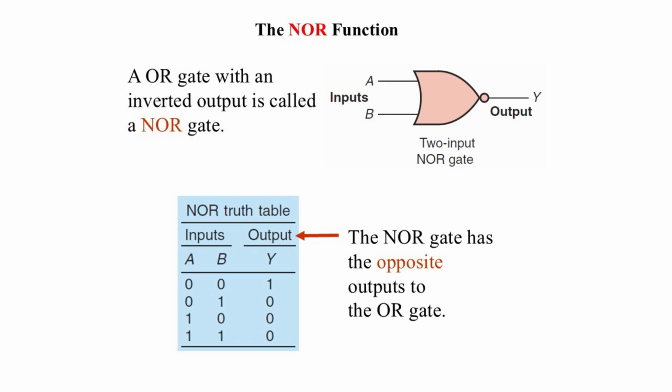In practice, this means the NOR gate acts like a none-of-these detector. The output is high only if none of the inputs are active. For example, in a PLC safety circuit, a NOR gate could be used to ensure an output is energized only when no fault signals are present.